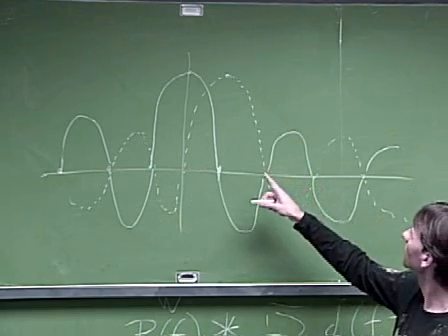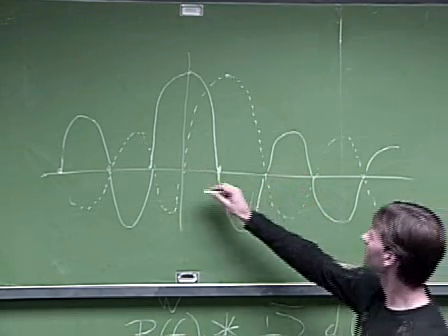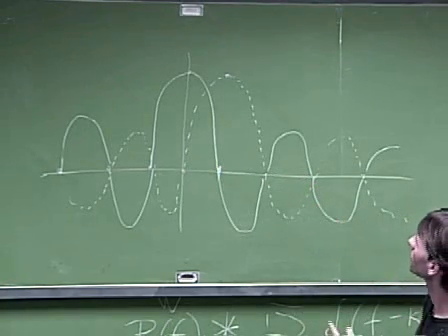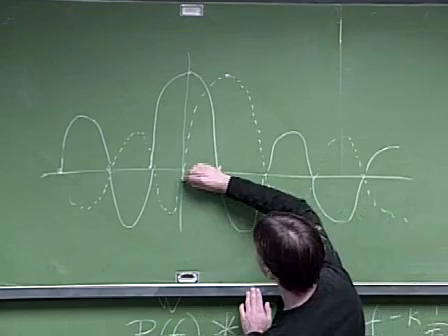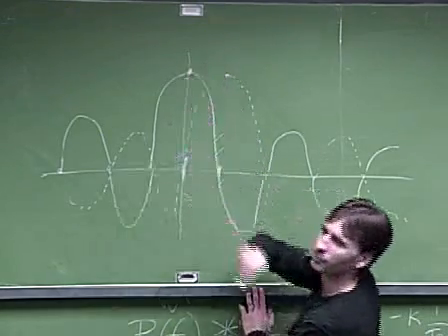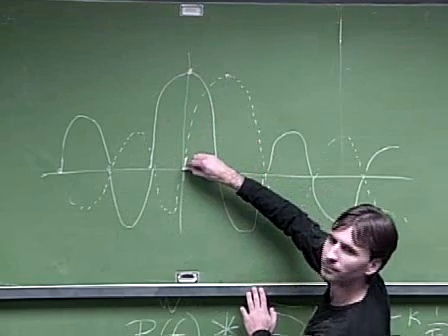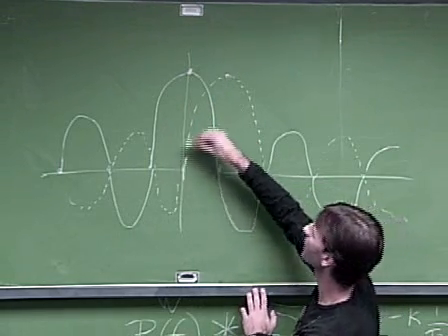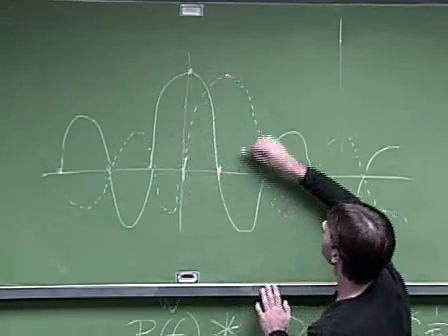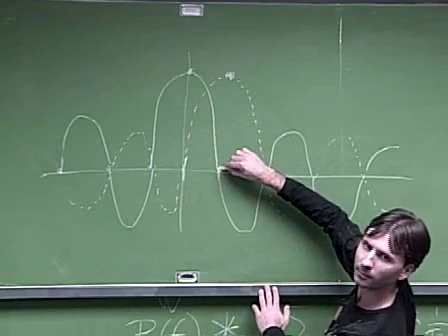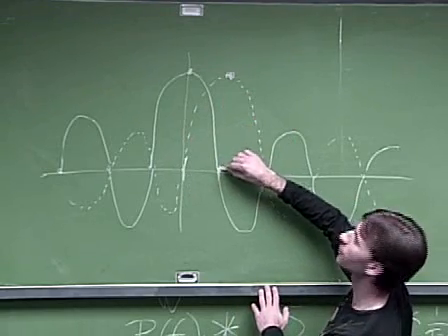But you see the zero crossings are lined up precisely, right? So if I sample at this point in time, I'm getting this guy's information, but this guy is giving me 0. You see? So they're not mixing. I'm not mixing them up. I'm just picking up this guy. Now, in the next symbol time, I'm just picking up this guy. The other one is giving 0 here. So they don't interfere with each other, right?